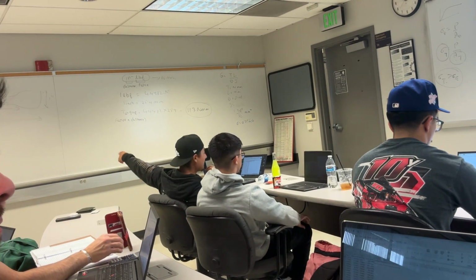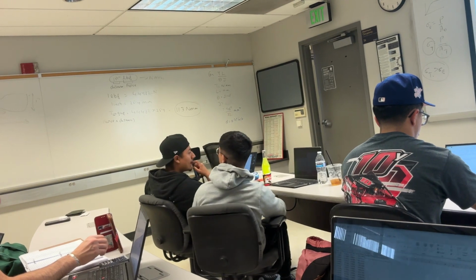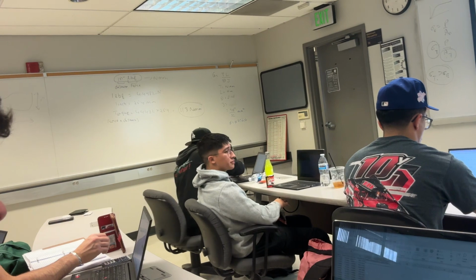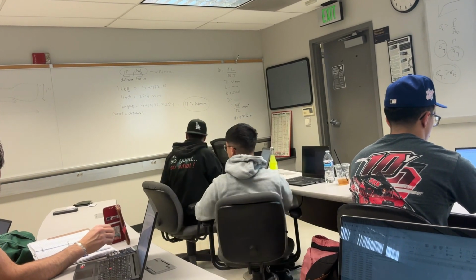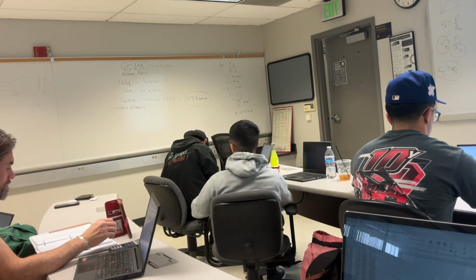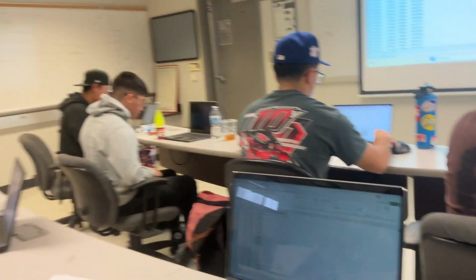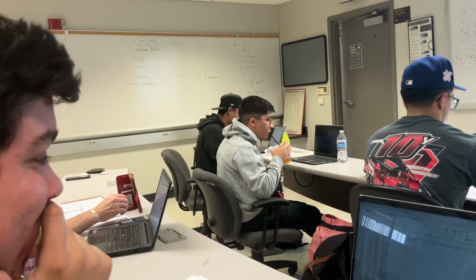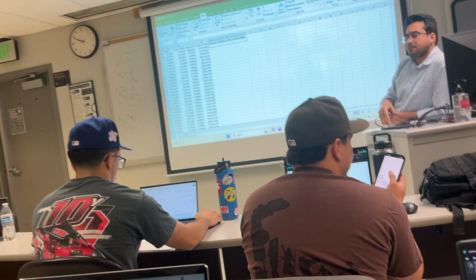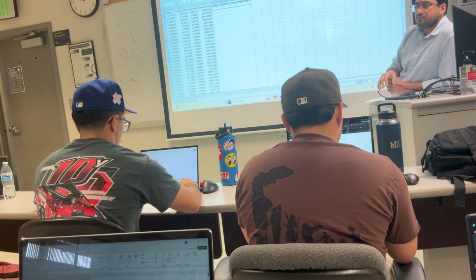I did the conversion right here. 19.05, yeah. That's a different number from the 304.8, which is for length. And then I took the fourth power of that, multiplied it by pi and divided it by 32. That's fine, you use yours.